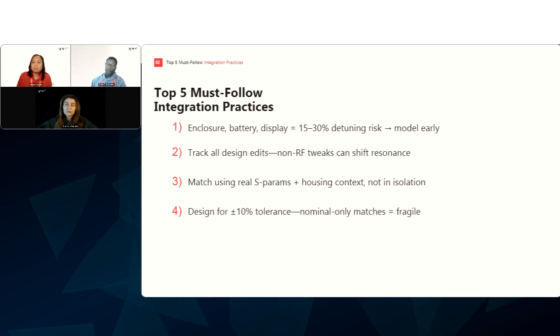But just to circle back, I think the discussion we had earlier had more to do with moving from simulation to a real-life product. So we always have some sort of margin. If you're getting 40% efficiency in simulation, in a real-life product, typically, once you've integrated all the plastics, the housing, the battery, and so forth, in free space you're probably getting about 30%. And this is due to parasitics on the board, right? Because at that point, you have a multi-layer design and a lot of interconnects, and also just the tolerances of the components themselves.